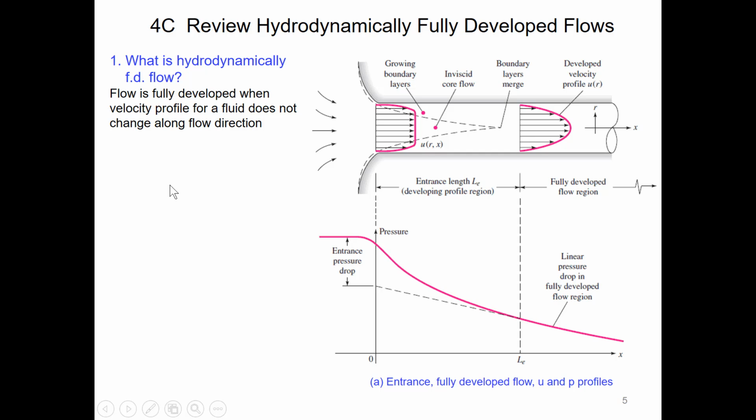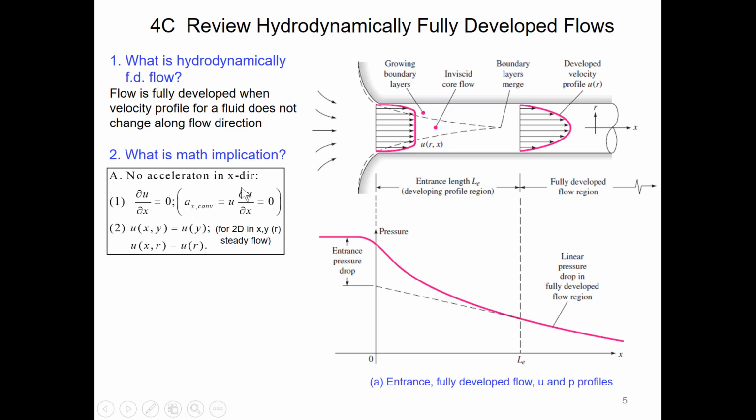There are three mathematical implications associated with the definition. First, since the velocity profile does not change over the flow direction, there is no acceleration. Therefore, the velocity in the flow direction, x, is only a function of y or r.